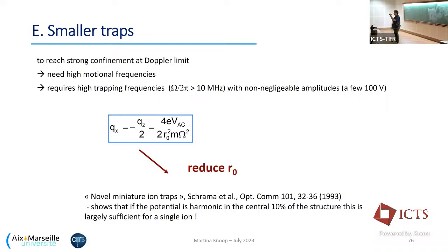It's also about technical limitations, okay? Because a vacuum feedthrough is always a capacitance which will degrade the helical resonator's performance. There are people thinking about other ways to do this. If you want to work out things on this q, you can juggle with the different entries, and one of the things is to go to a small R if you have a smaller V_AC, for example.